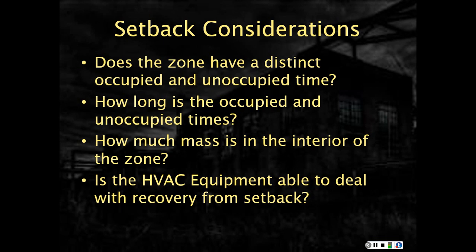The first one: the zone that I'm considering setting back, does it have a distinct occupied and unoccupied time? In other words, can I even use setback? Obviously, if a zone doesn't have unoccupied time, in other words, there are people in there all the time, setback doesn't even come into play. How long do the occupied and unoccupied times last?